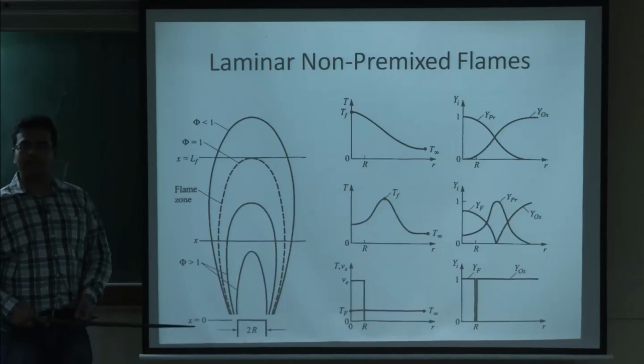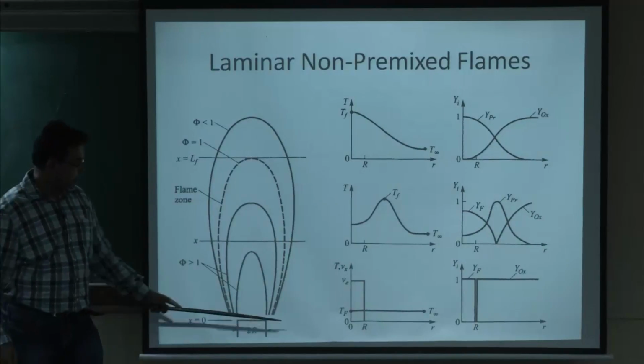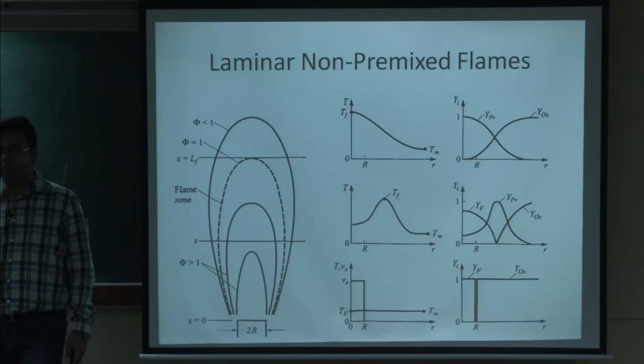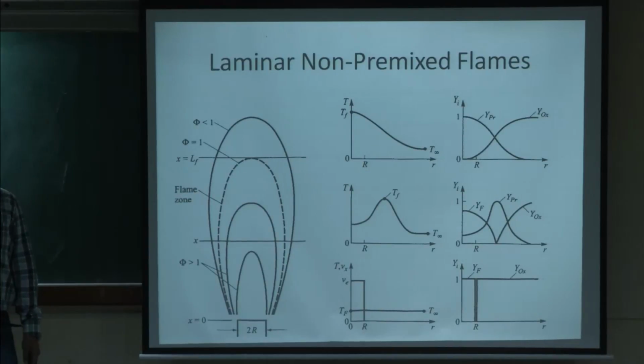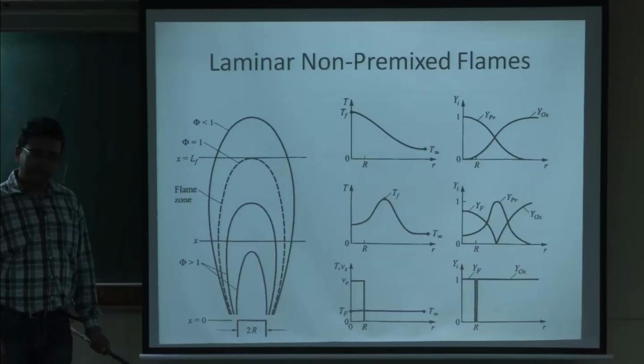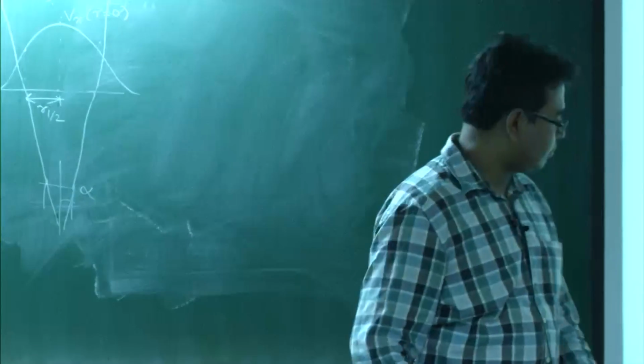Again the oxidizer can be pure oxidizer, or it could be a burned product, okay. So, you can have a premixed flame before, and you can have a burnt mixture as an oxidizer with some amount of oxygen left in that, okay. So, these are the possibilities which we can have, but now we will stick to the simple thing that we have a pure fuel jet, and that is coming into a pure oxidizer, okay.